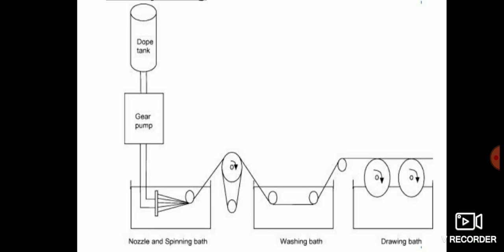Being extruded into a liquid provides a greater drag force on the filament than those extruded directly into air. Therefore, the speed at which this occurs is reduced from that of melt and dry spinning. Once evaporated, these fibers then have to be drawn or stretched in order to orient the polymers to give fibers its strength. The fiber solution is extruded into a liquid that will draw out the solvent, leaving behind only the